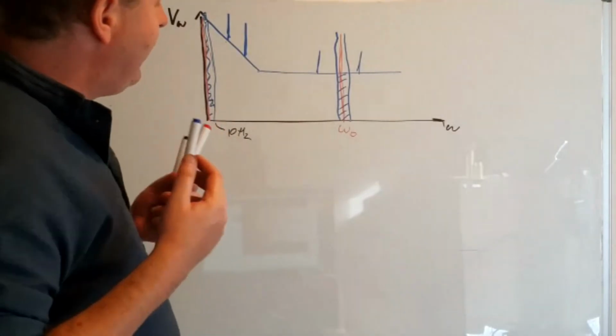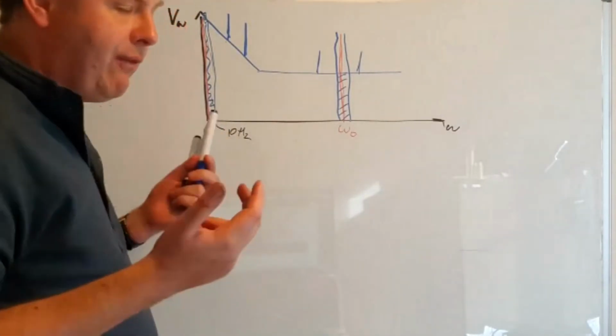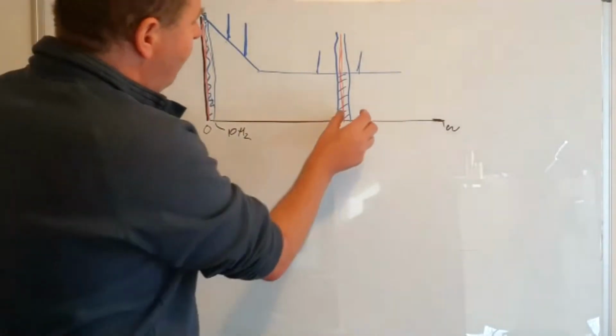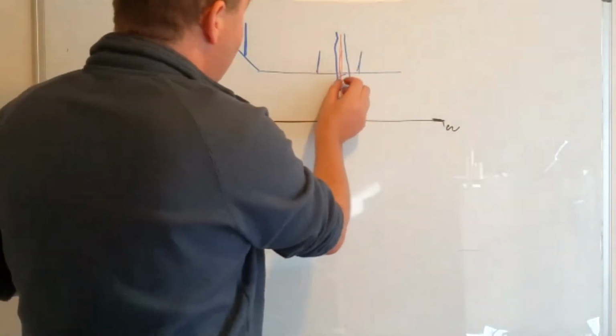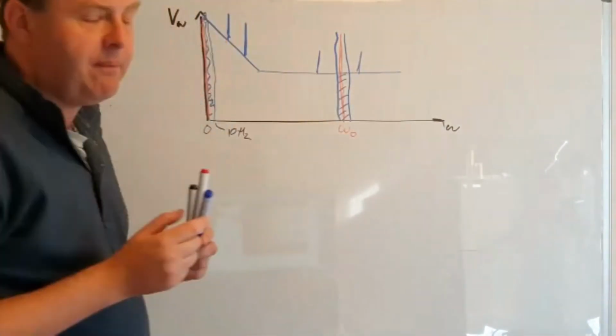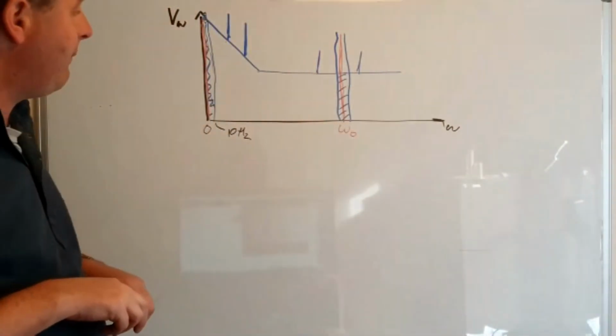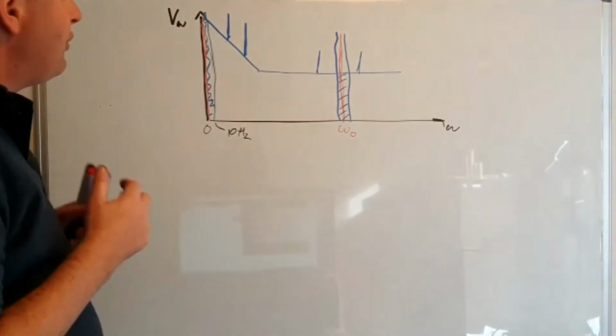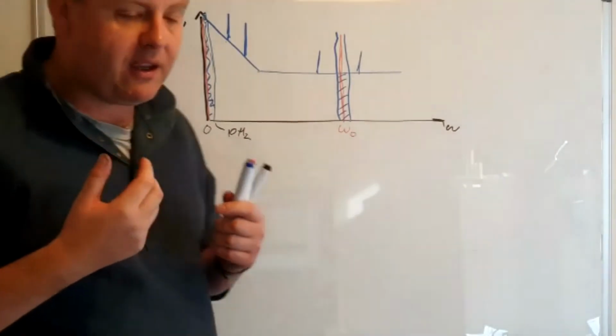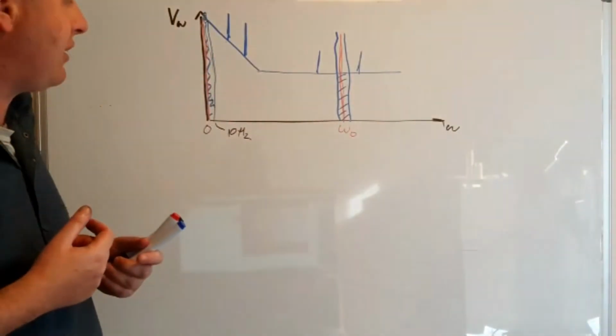And if we increase the amount of time we average for, we reduce the bandwidth, and therefore we narrow down this blue rectangle here, and we include less and less noise and retain just the bit of the signal we're actually interested in. So this is really the power of phase sensitive detection. And you'll find phase sensitive detection is being used in many, many experimental situations.